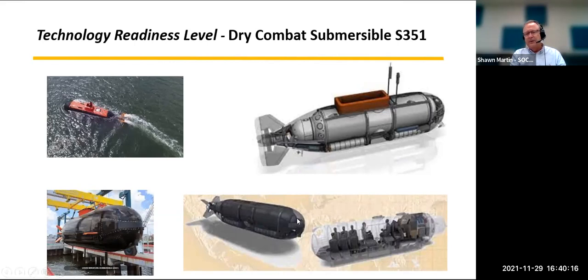The sonar as well, which is really right under here. That is like a bumper, to be honest with you, attached to the pressure hull, and under here is the sonar. And right here is the sonar window, acoustically transparent material. That was also at a lower TRL as the first article prototype build. It was built by the University of Texas Advanced Research Laboratory, UTARL, an FFRDC, a federally funded research and development center, and they have extreme expertise in sonar design and fabrication.